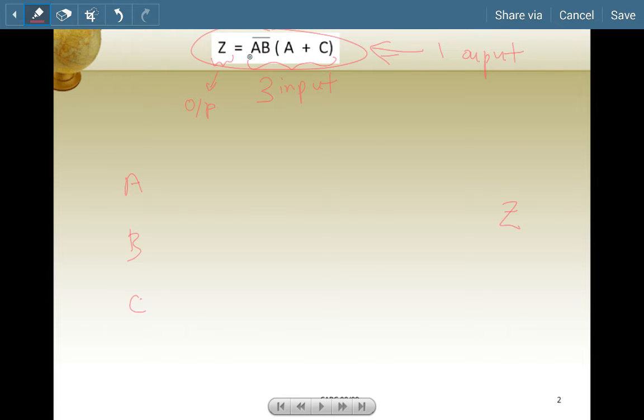That reminds you that eventually, near the output, near the end stage of the transformation process, you need to use an AND gate. It will serve you well to remind yourself of that by drawing an AND gate at the end, so that you will not be lost as you start working on the individual inputs.